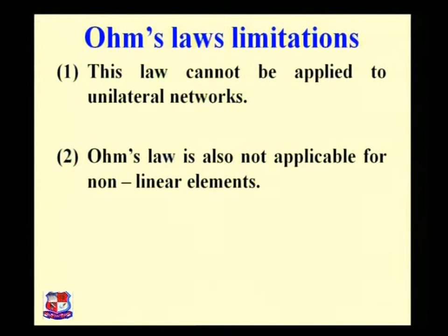Another limitation is that Ohm's law is also not applicable for non-linear networks. As we see, both points are quite similar, but the difference is that one is a unilateral network and the second is a non-linear element. What is a non-linear element? Diode, transistor and SCR are all non-linear elements. So this law cannot be applicable for diode, transistor or SCR-like characteristics.